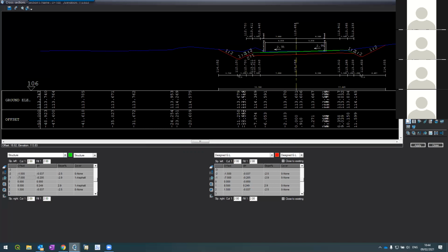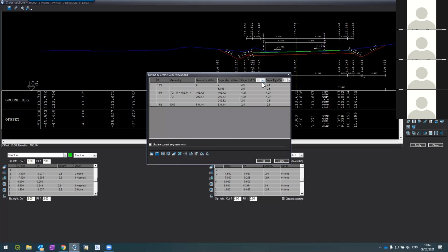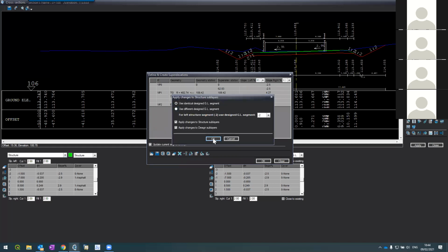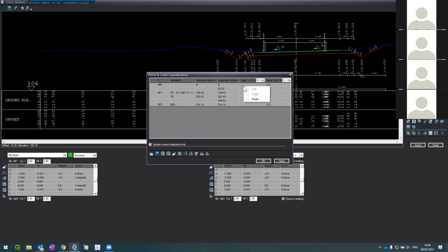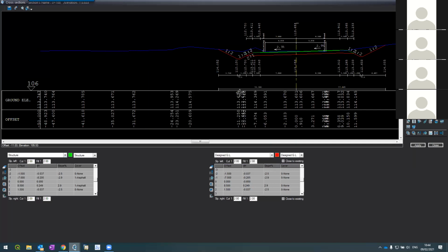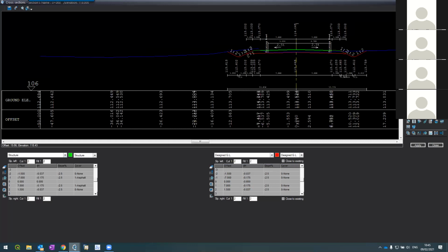But then when she did the super elevation, she had 2 segments, and the system automatically suggests only to do -1. So I tell her, in this case, you have to take the suggestion in the software, copy, go to -2, press OK on this one, stand here and press paste, because the 2 lanes are following the same. In fact, if you want your shoulders to super elevate as well, this is what you will have to do. Again, just practice it and then you'll see it.